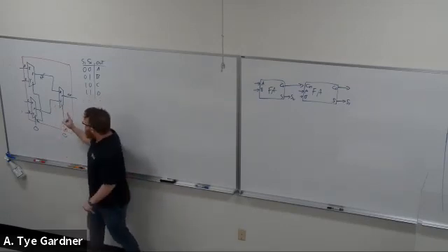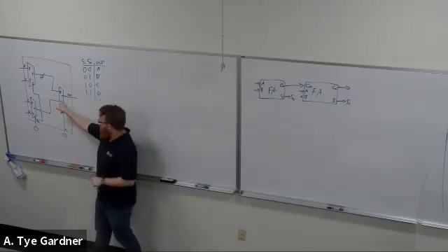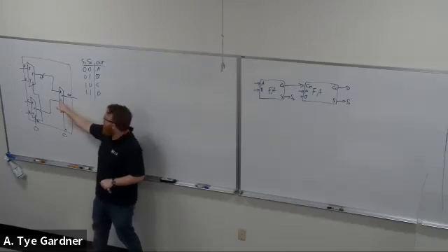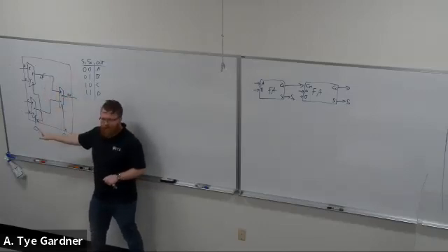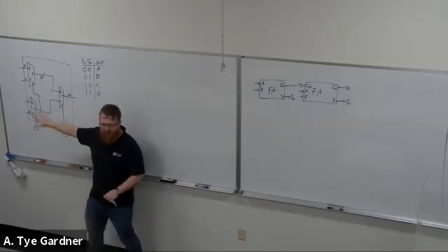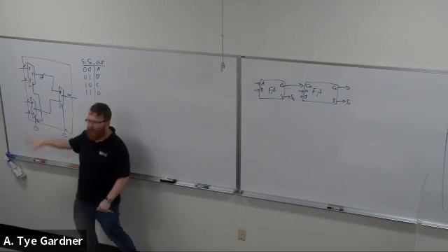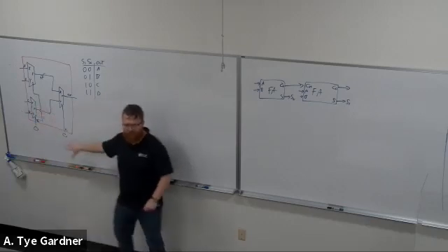Okay, so we're going to build in modules. My mux is going to be one module, and this red box is another module. Okay, I can then, if I wanted, you could quickly imagine if I stick a couple of these in parallel, I can then build an 8 input mux, right? And then there would be a structural description of how those connect.